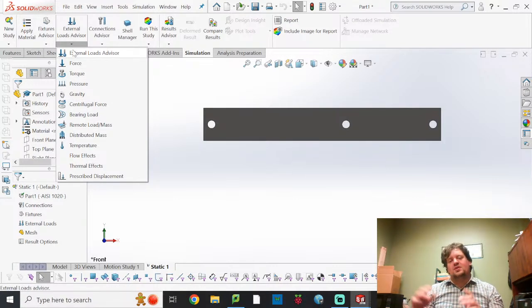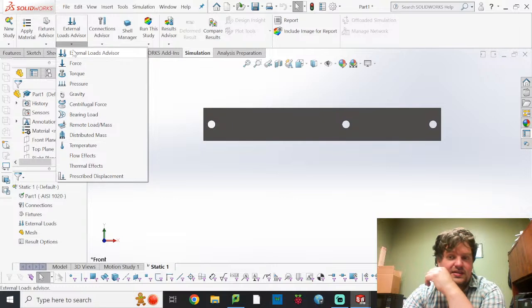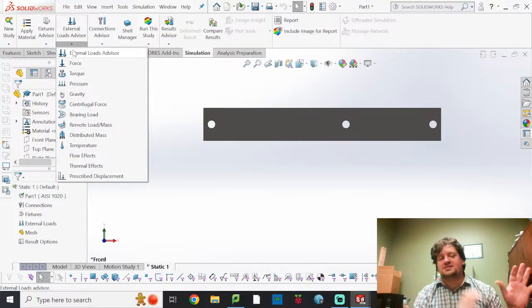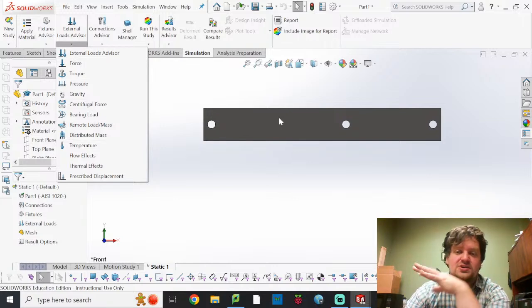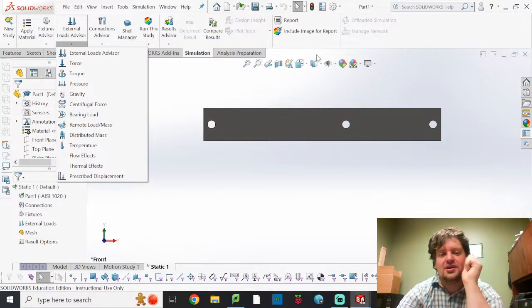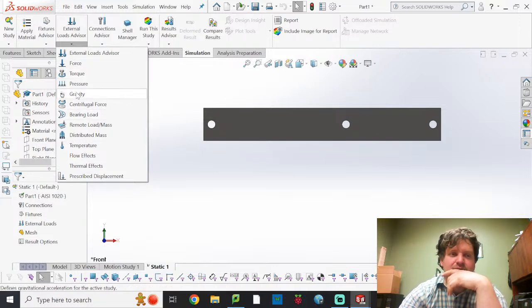Now, as I mentioned, you model from the end of the hammer moving backward to the motor. So in this one, if the right end of this component goes to the hammer, and the left end goes to the 4-bar linkage that connects to my motor, then my load is going to be applied from the right end and my fixed end is going to be on the left. So you need to know how force is being transmitted through here, which end is being loaded, and which one is more passive, just accepting that load.